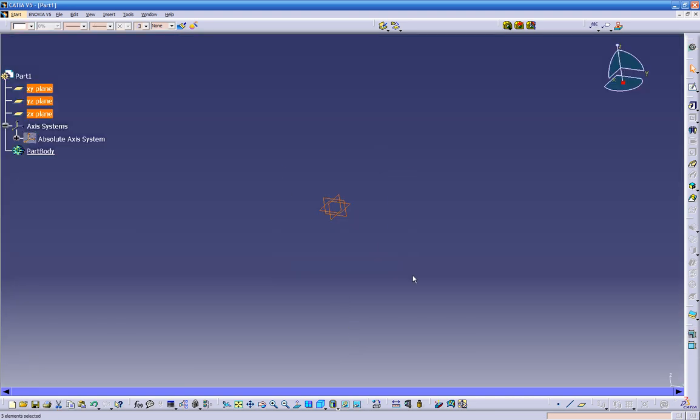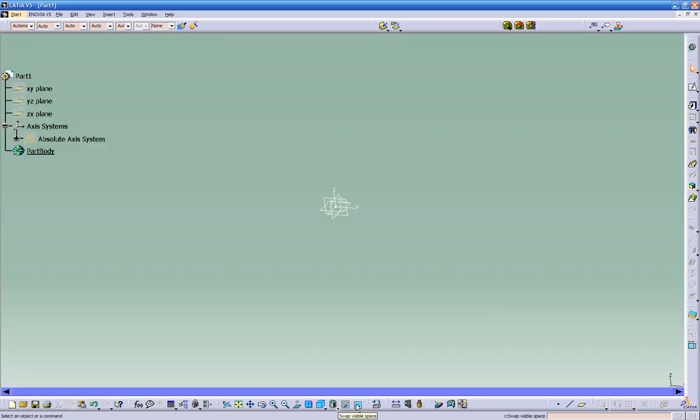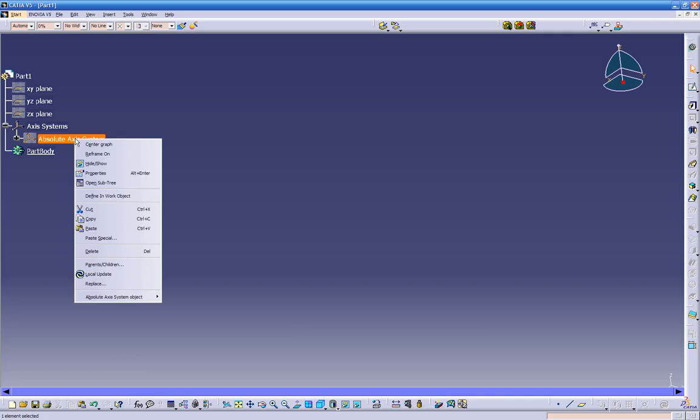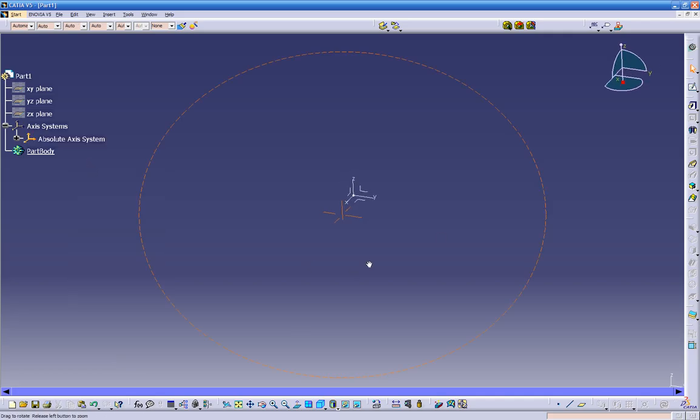And if we highlight this, we want to throw it in a blank level, we just click hide show, and everything right now it's in no show level. Okay, so let's click swap again, and let's click a right click over here, hide show. Let's bring the axis back. So we got our axis. Right click again, hide show. So now we bring it back up again.